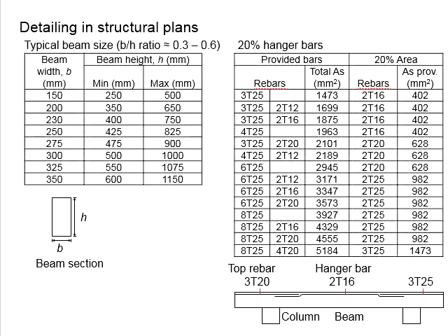Now you need to provide reinforcement bar to take the stress, both in tension and compression. You know that concrete is weak in tension. That's why you need to provide a lot of reinforcement bar at the support. However, concrete is really good in compression. Most likely the concrete itself, if you provide an adequate size of beam, is already sufficient to withstand the compression stress.